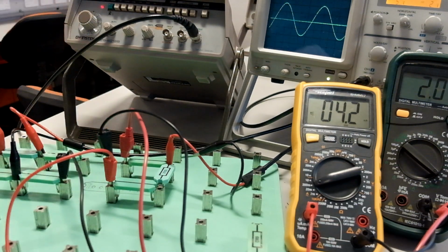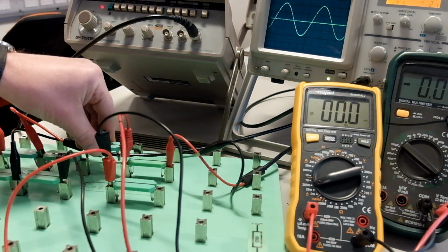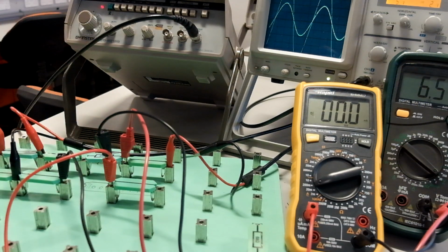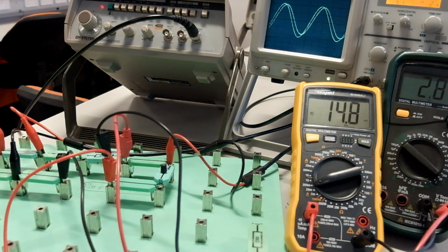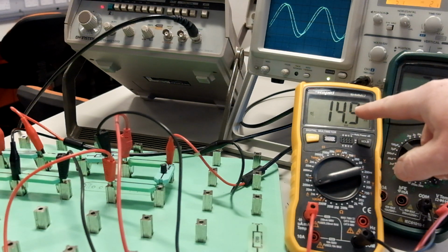Now what if we want to get the voltage across the inductor? We can swap these two components over without moving anything else. The prediction was 2.83 across the coil voltage, and what we get here is 2.83 across the coil. That current hasn't changed. So the voltage across the inductor appears to be correct, but the voltage across the resistor is way out and the current is way out.